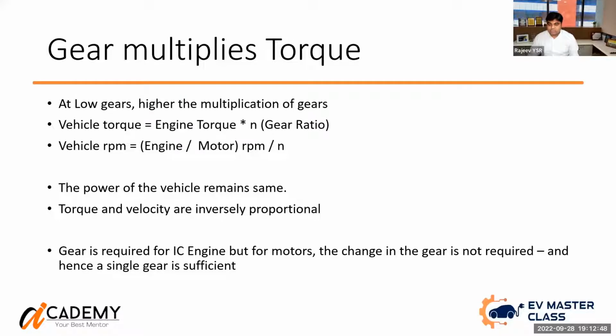Power is equal to, what is power, guys? Power in the angular world. Power is equal to torque into angular velocity, correct? So assume that the power is constant, and you need more torque. So if the power is constant, torque is inversely proportional to the velocity.